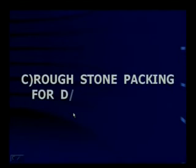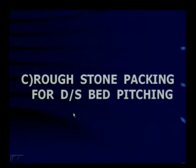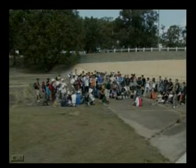The next and the last item would be rough stone packing for downstream bed pitching. It is a similar item as in the previous case of upstream bed pitching. You have seen here, these are students making a tour to a site where a culvert is there. You can see all of them standing on the apron here. I've just picked it up for you to see the real site image. The place where they're all standing is the apron. Just multiply with the dimensions and you get the quantity of bed pitching to be done on the downstream side also. And let us see the figure now.